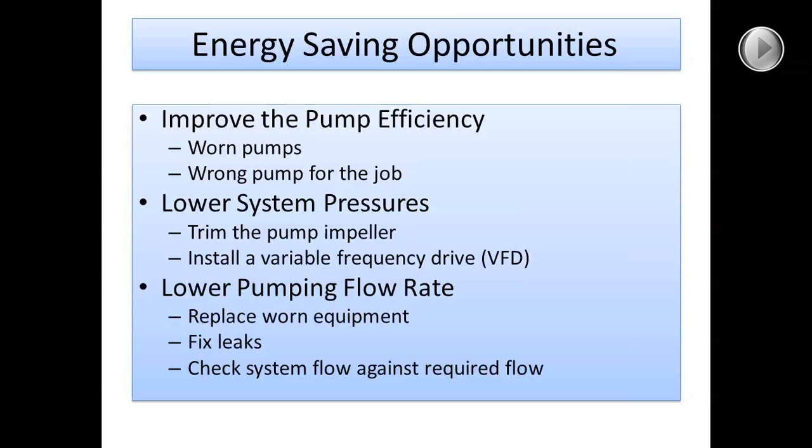We'll talk about those a little bit today. If you're not familiar with VFDs, they're called variable frequency drives, or variable speed drives. There are different styles. But basically, with a variable frequency drive, the main application that I see is you want your system to operate at a certain pressure all the time. Whether or not you're running at full flow, you'll usually be operating at full speed, your design operating pressure.